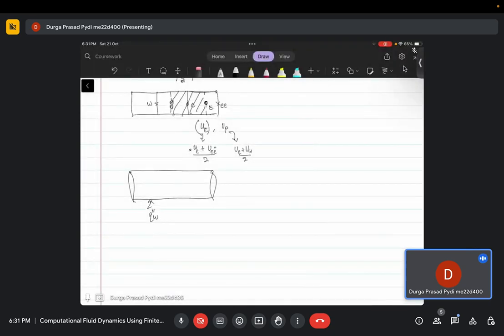So this was your problem, right? You have some pipe flow, a fully developed flow through a circular duct with some constant heat flux. You essentially need to find your Nusselt number on the wall. If you're defining it with respect to your diameter, you know the K of the fluid. The only thing that you need to find is your heat transfer coefficient.